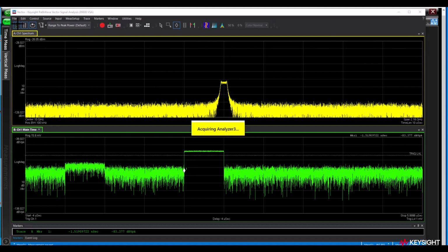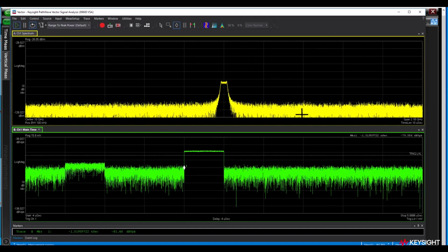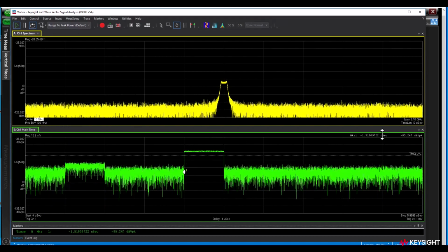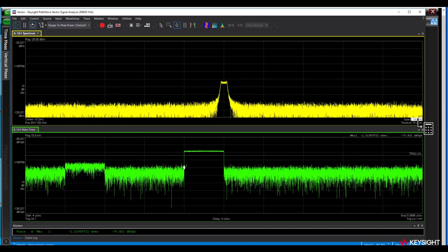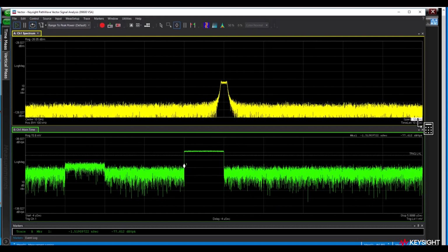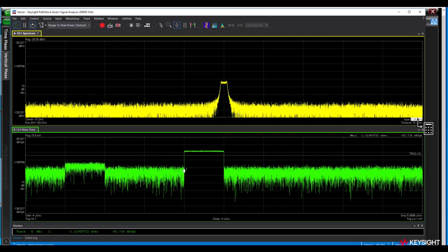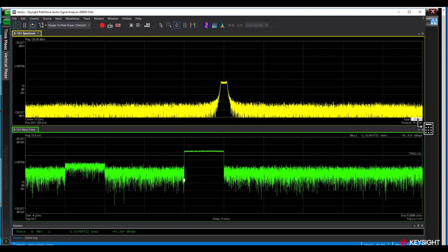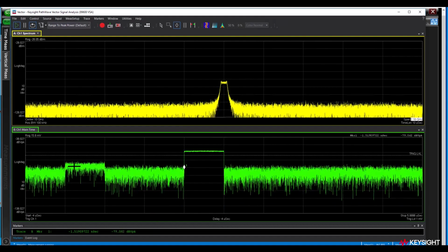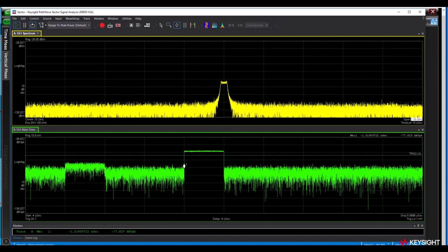So I'm going to hit run. These are the same exact two signals, except now, as I mentioned, we're using the real-time digital down conversion, and I'm tuned to 10 gigahertz. I have a span of 2.16 gigahertz, which is much less of a frequency range, so lower noise than when I had 33 gigahertz. But the pulse, this minus 65 dBm pulse, is still very noisy.